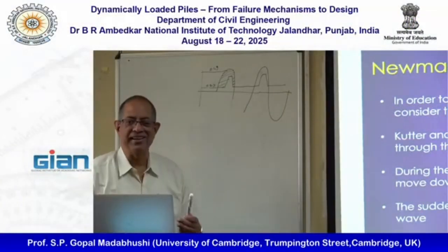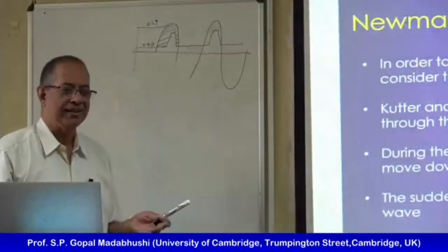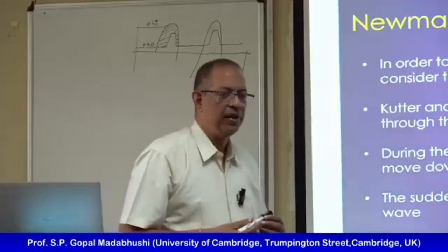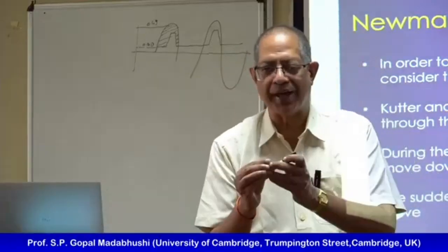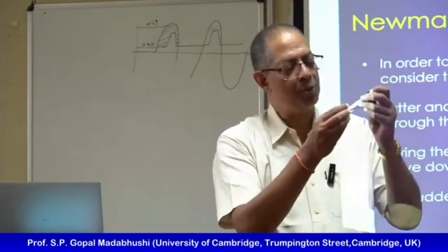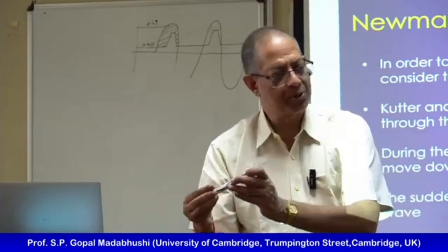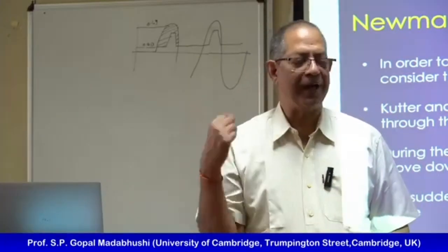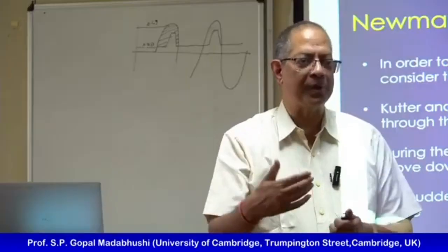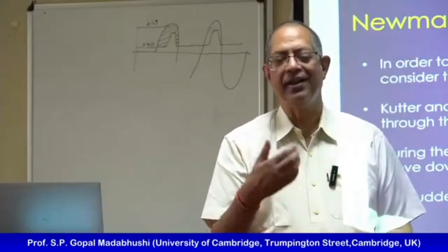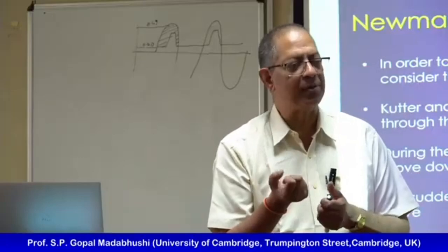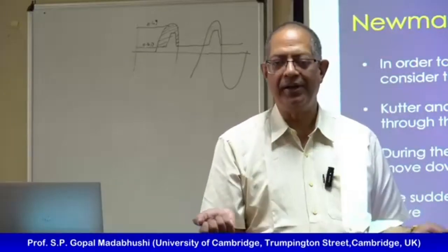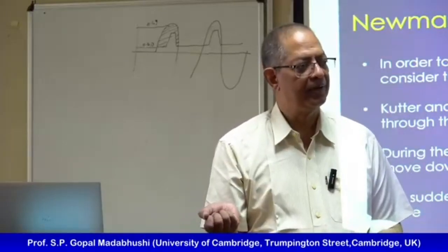So it will reduce the amount of lateral spread. And that is quite right, because what the suction is doing is stopping the slope from moving, right? So it moves, stops, moves, stops. If suddenly the pore pressure is going negative and stiffening my soil, I expect a smaller lateral spread to happen.